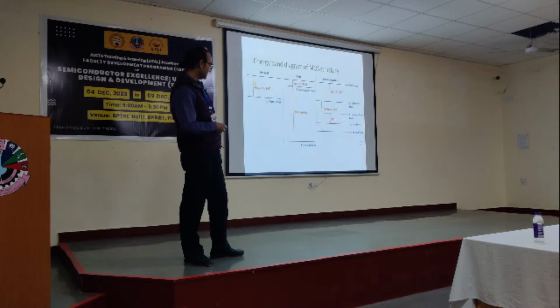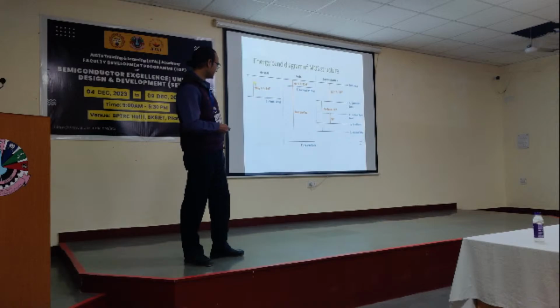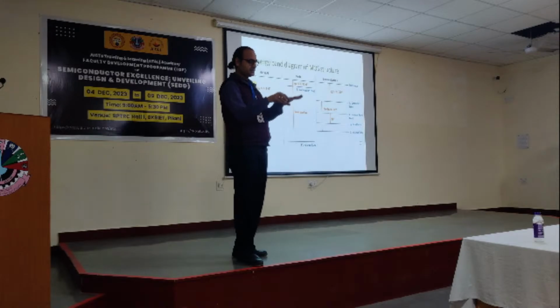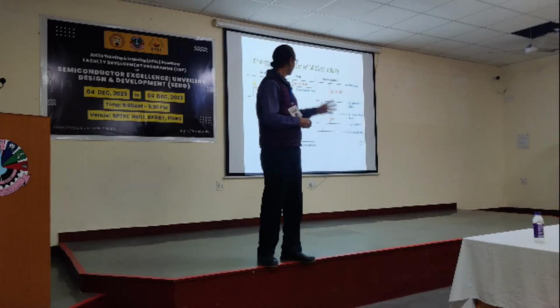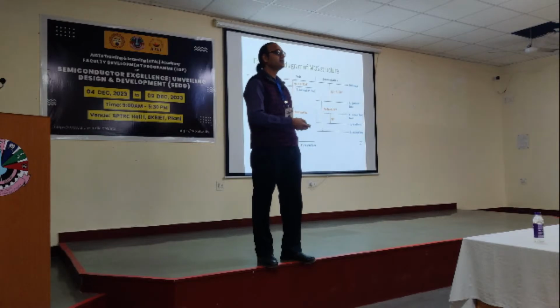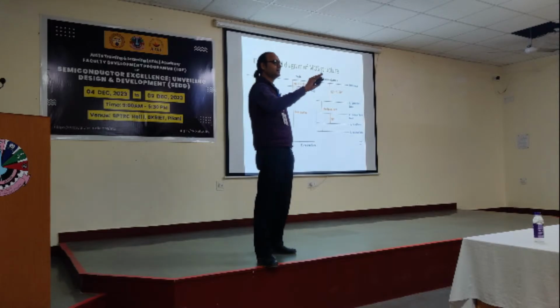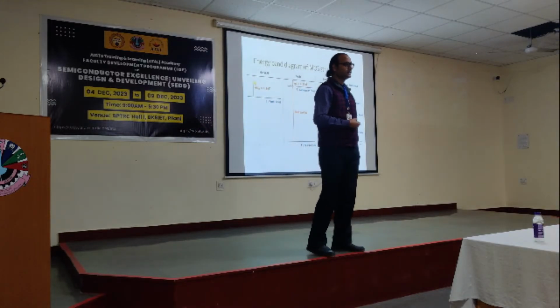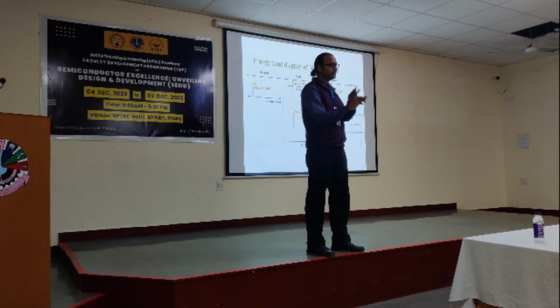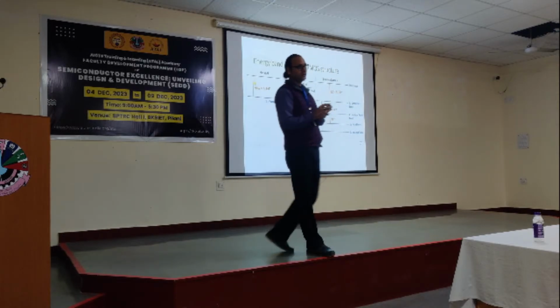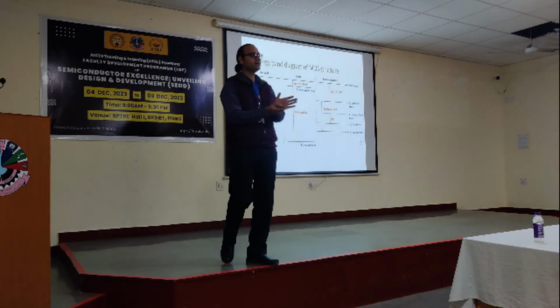And electrons getting out means generation of holes. More generation of holes means accumulation. So the band will bend like this now. We will say that initially the structure is under accumulation. However, in this case, I would say it is under depletion. So both things are possible, accumulation and depletion, depending upon the work function of the metal, the type of metal. That's why we study a separate topic like metal and semiconductor.